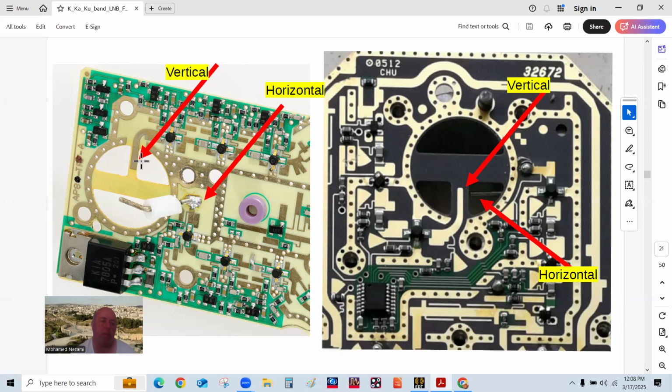Okay, and I'm sorry, the other way around. That lid becomes a cover short for this one here. No, for this one, I apologize. The back short for this is basically this here. Okay, and this here, this is the top. On the back of that it's really covered with copper, and it's shorted because you can see the vias to ground in here.